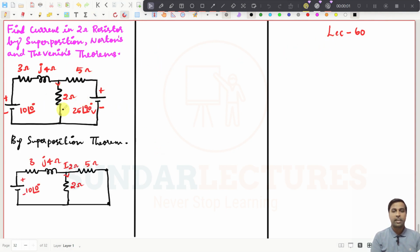Right, now we have taken this example. We are going to solve this problem by the superposition theorem, right? In the superposition theorem, we need to deactivate one source, and then activate the other source to find the current in the 2 ohms resistor. Now I have deactivated this source, this 25 at an angle of 90 degrees. Now we need to find the current in the 2 ohms resistor by the 10 volt source only. This is a simple problem.